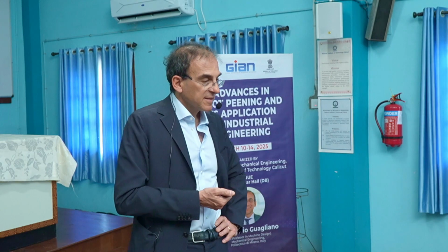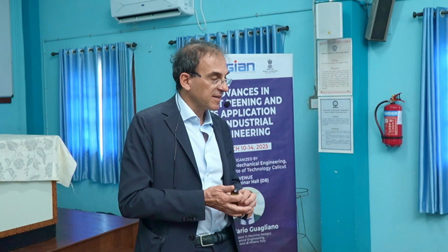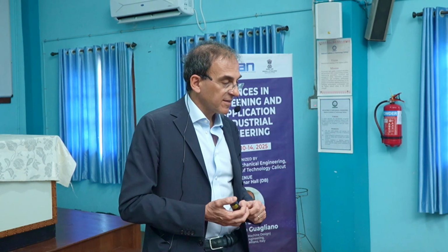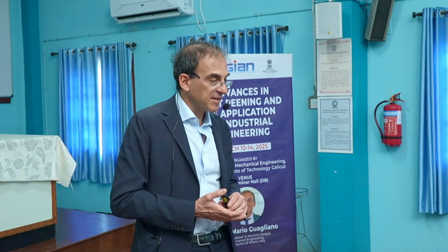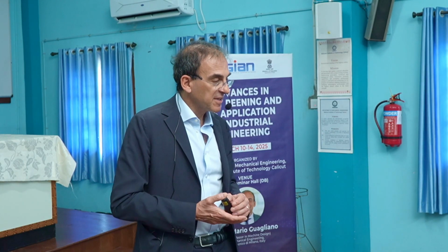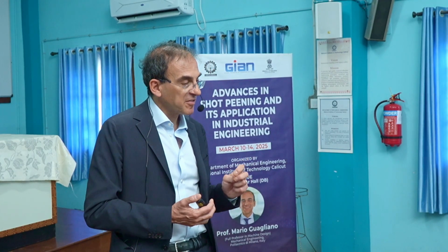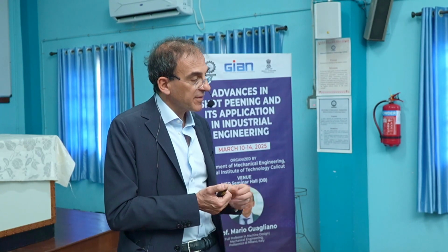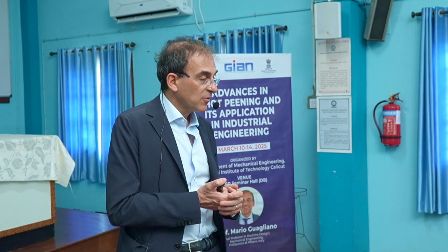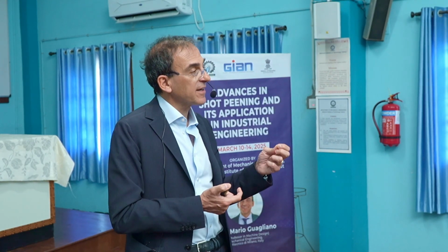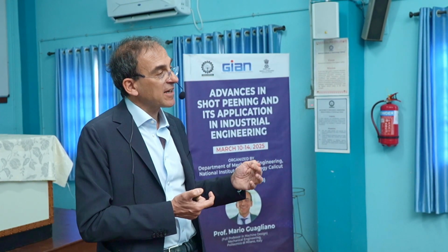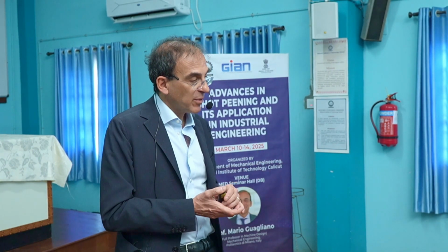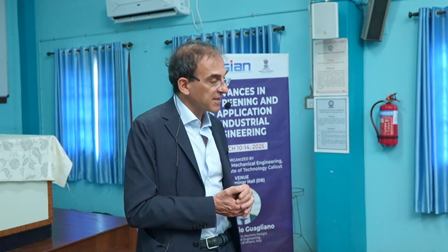We have fatigue life increasing on the vertical axis and hardness on the abscissa, and we see that the role of residual stresses is getting more and more important for harder material. Why? Because in this material they are less prone to relax after the application of fatigue cycles. Anyway, both these effects should be considered.